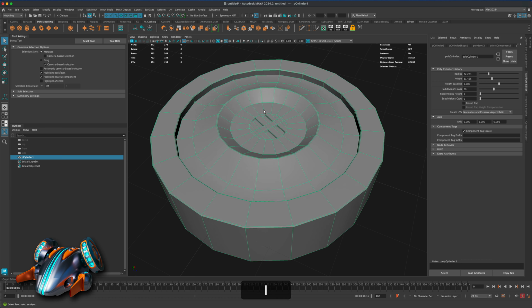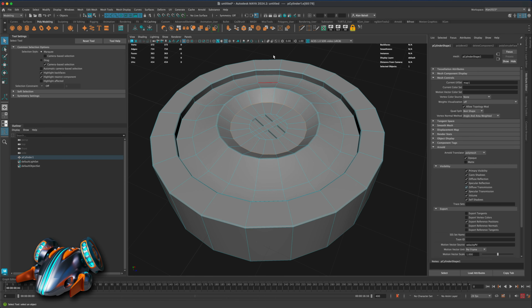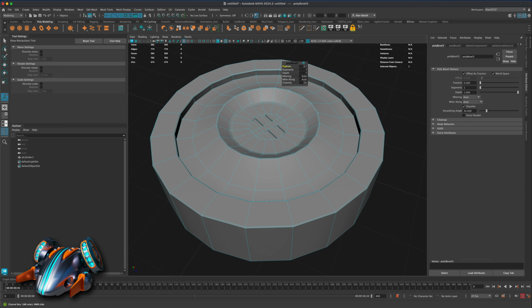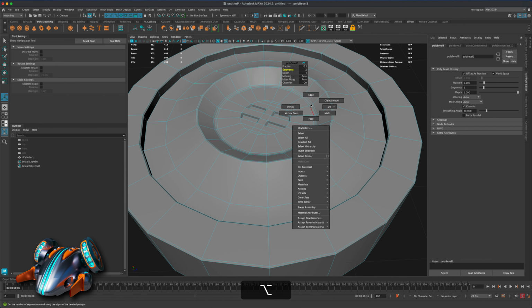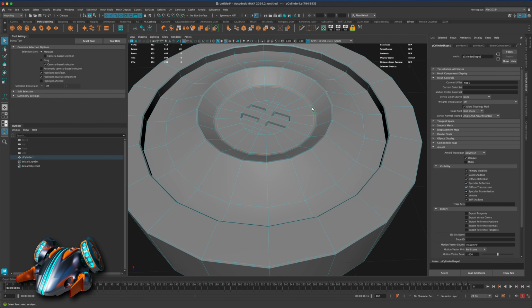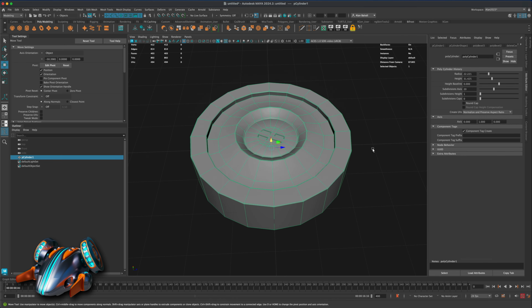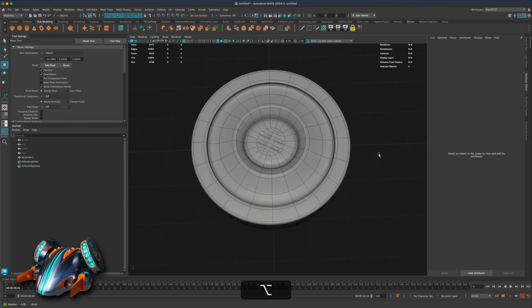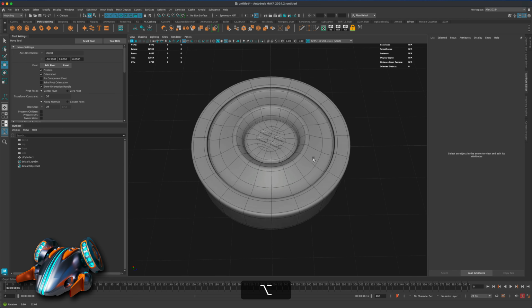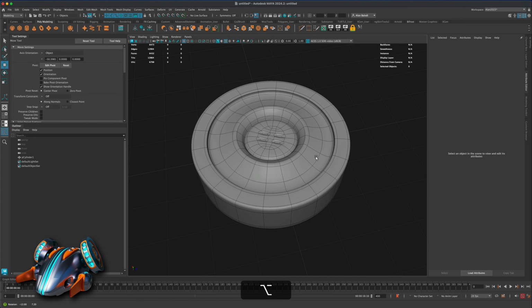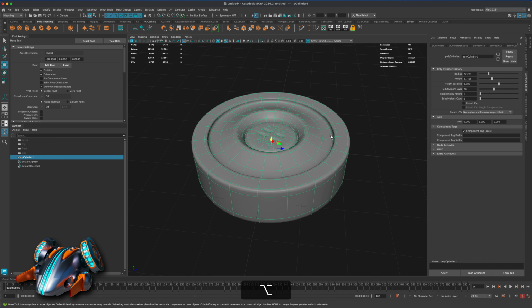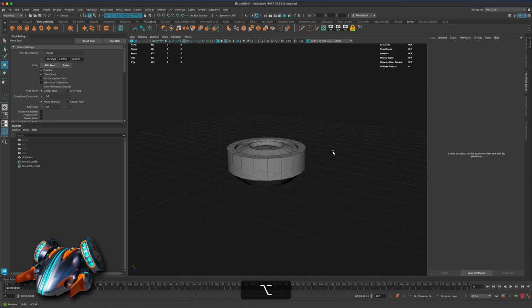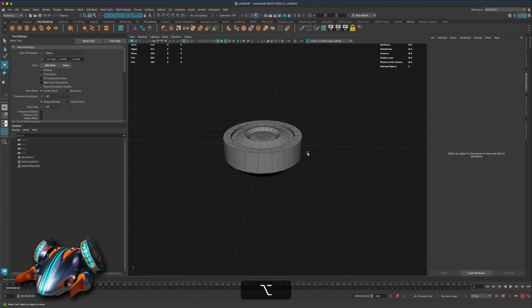Let's do, I'm going to press 1, double click on this, bevel, turn this maybe something like that. And you know what? I'm going to add a segment there as well. And I'm going to take this extra segment, press W, and pull this down. Okay. Go to object mode, press on our shape, and let's do a quick preview and see what that looks like. I think that's a little more interesting, right? It just adds like a fun little inset in there. Very cool. Press 1.